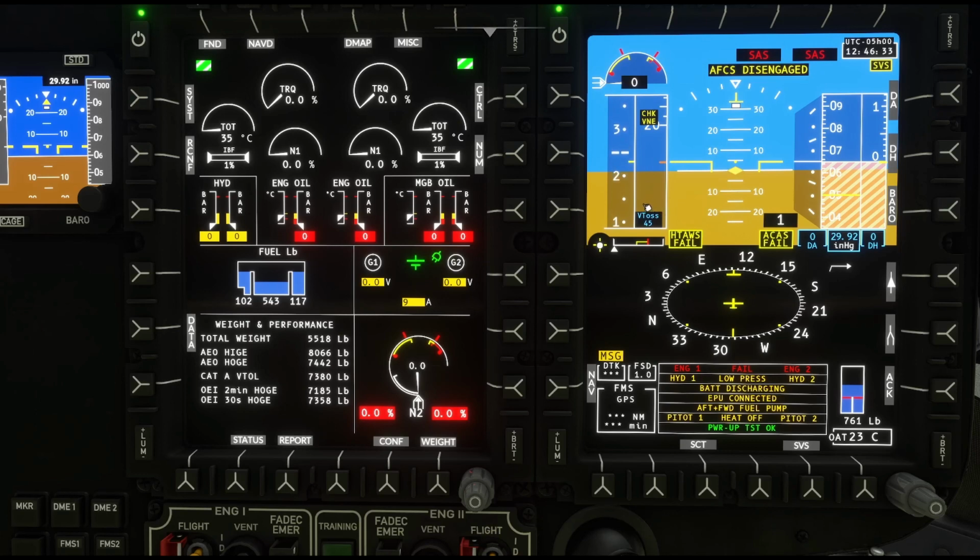So being a low inertia rotor system, if you find yourself in a situation where you must enter an autorotation, it can get away from you very quickly. And in the older version, the C2 version of this aircraft, which had the same rotor system, when you entered an autorotation, you had to be Johnny on the spot in order to get into an autorotation without drooping the rotor system in the event of a dual engine failure. But at the same time, you really had to pay attention because when you drop that collective, that rotor would go through the roof really fast. So you had to catch it. So now you're flying along and you just bring it down to 2.5 FLI, a little bit below it, until the rotor starts rising, and then you know you have to stay right along in here.